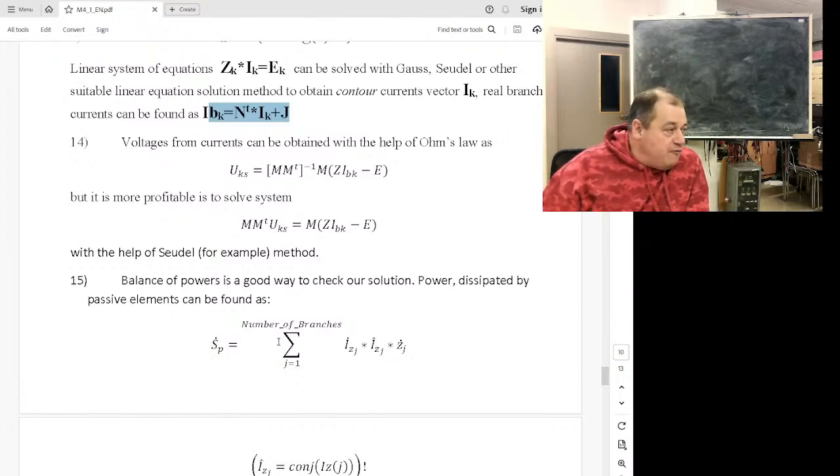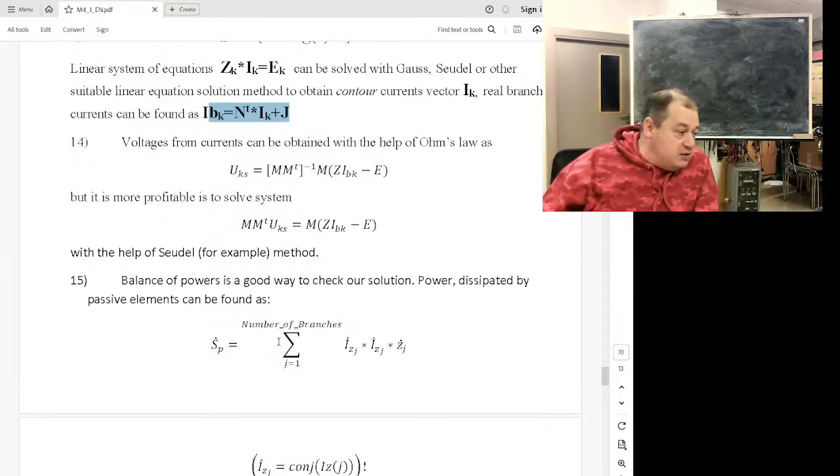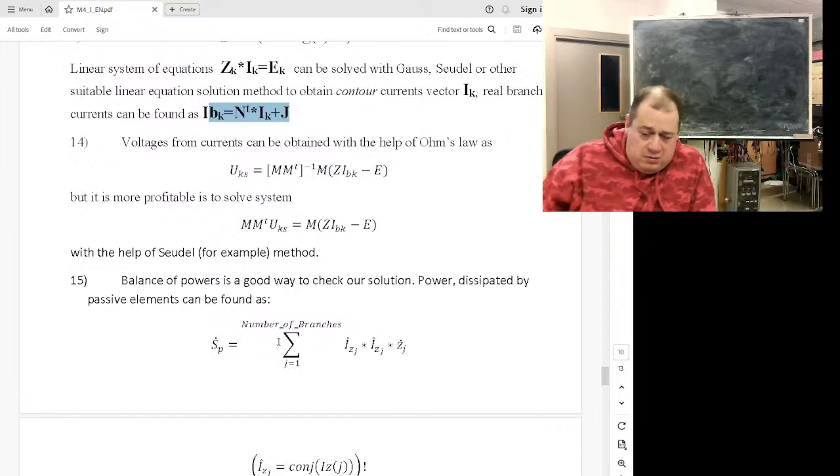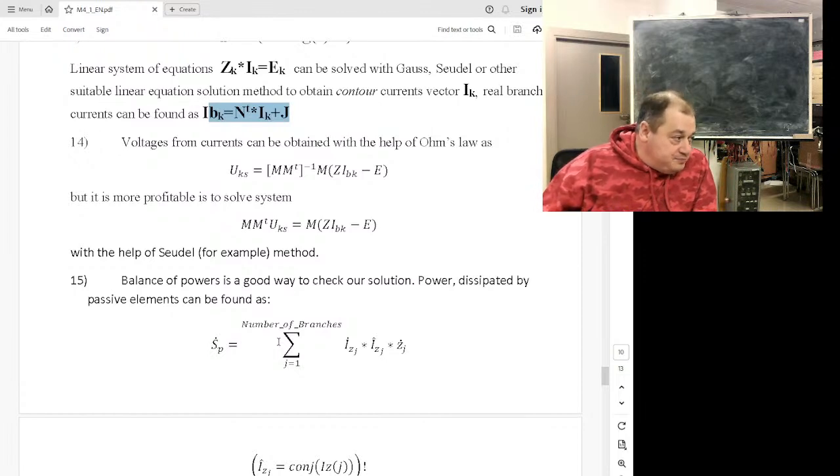To get full power, here power, as we saw, red line, consists of two parts. One yields positive, in my case positive heating, and one corresponds to just charging a capacitor and discharging a capacitor, a kind of oscillation of energy. It's called reactive power. Active power is real.